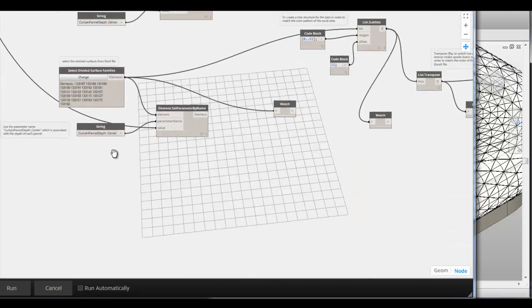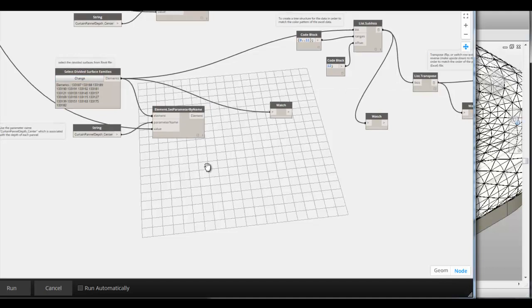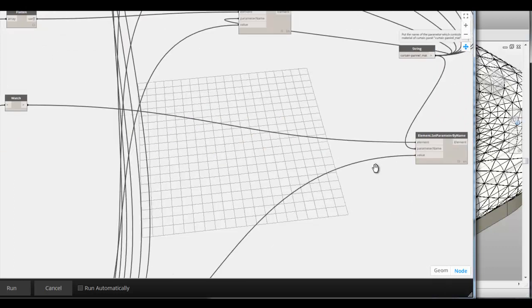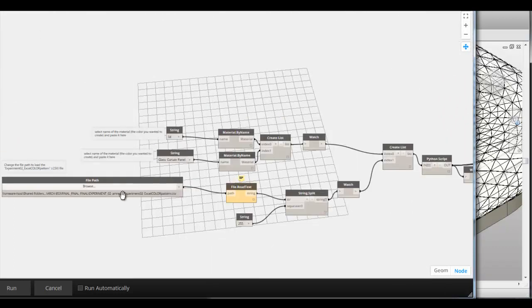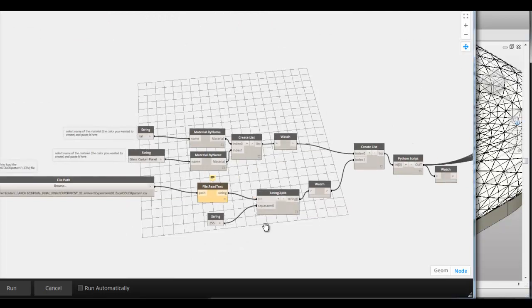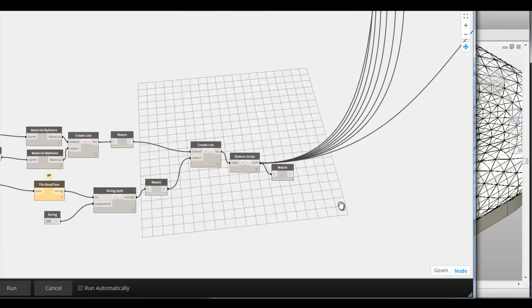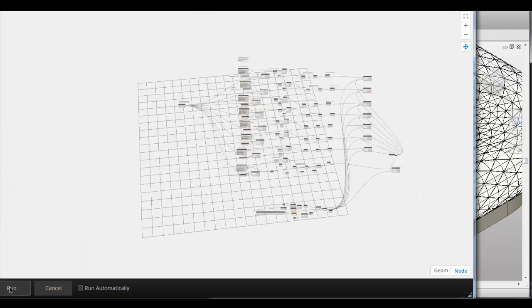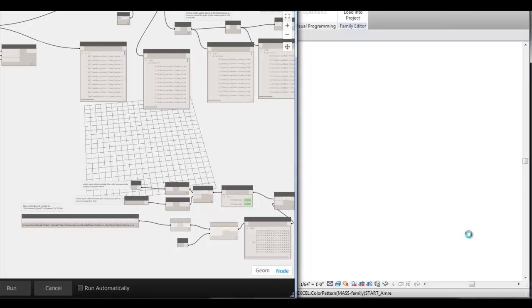If we see in detail, there are 8 curtain panels which have been linked with Dynamo, and a separate data structure has been created in the Dynamo file. And finally, the Excel CSV file will override the existing material of each panel by creating a pattern surface. Now, if we hit run to see the outcome, then we will see that a different pattern has been generated.